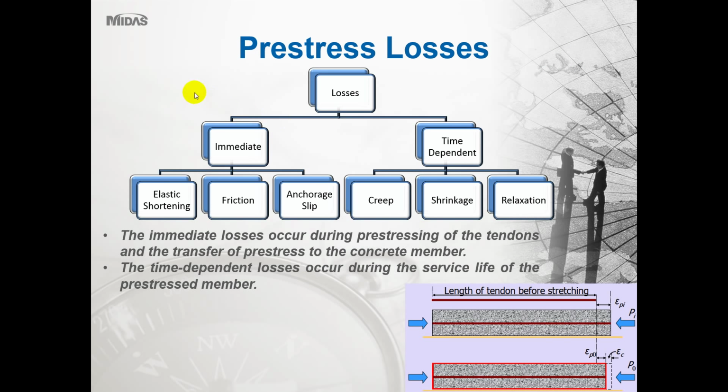So now just going on to prestress losses. Prestress losses are critical for the analysis and the correct tendon force to be applied. Sometimes, if you have dealt with it before, you can get up to 20% losses in the tendon profiles. There are basically two categories of losses. You have the short term, and two, the long term time dependent losses.